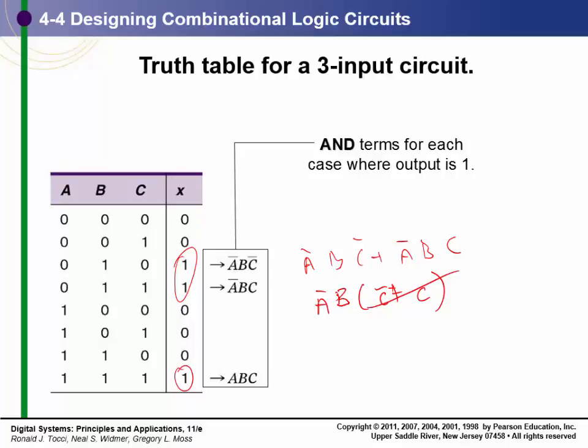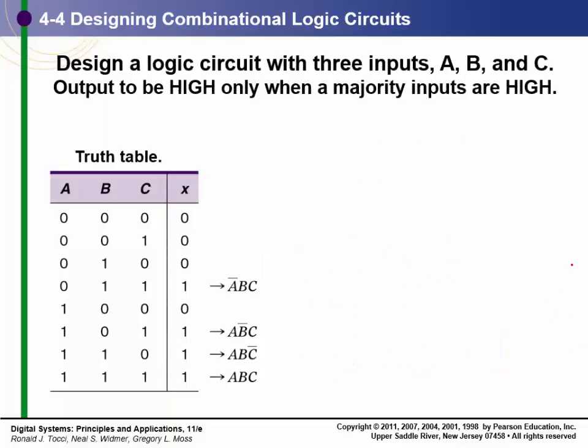The Karnaugh map is the way to do this systematically right there. And so we would have A naught B plus A B C, and that doesn't look like it's good. I could factor a B out from there. That doesn't really save me much right there. This is equal to B times A naught plus AC right there. And actually this would factor out then. That goes back to that other form that we had right there. So we could factor this out right there.